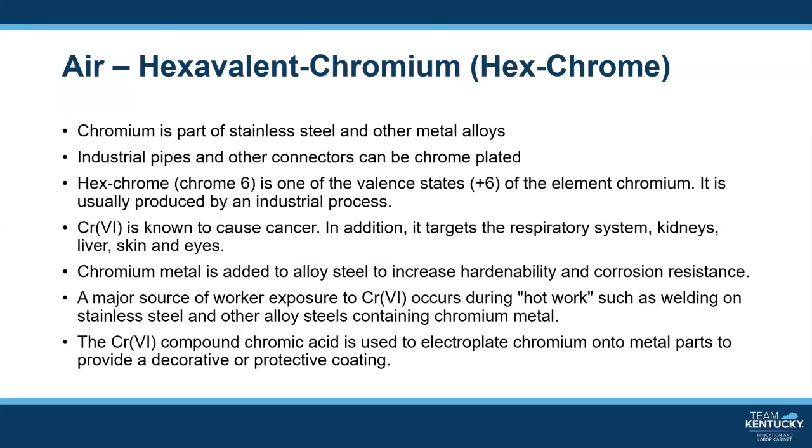Another health hazard that could be present in a work environment where welding is occurring is hexavalent chromium. This is also known as hex chrome. It could also be known as chrome 6. Chromium is part of stainless steel and other metal alloys. Industrial pipes and other connectors might be chrome-plated to prevent corrosion.